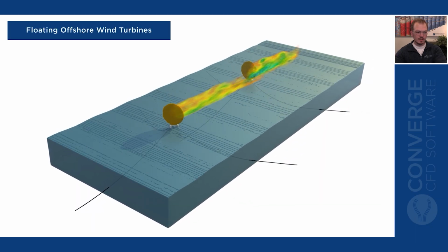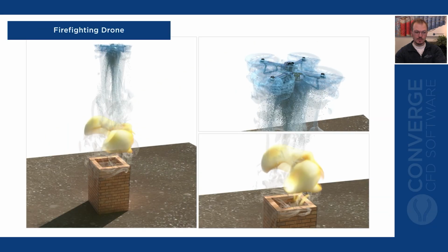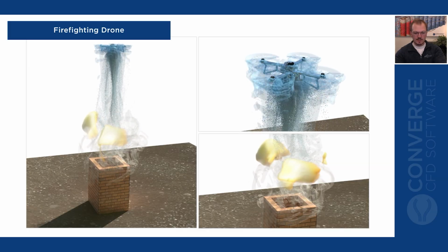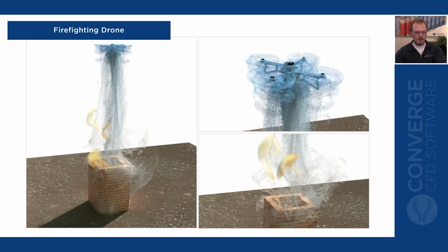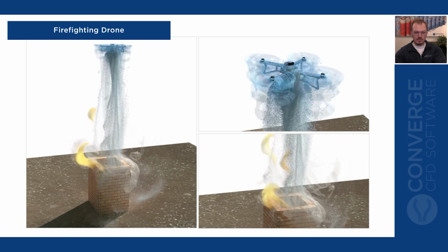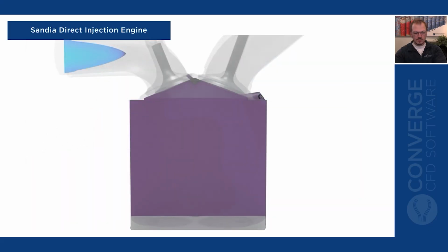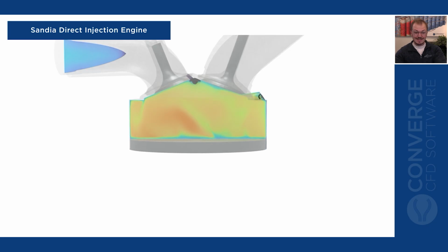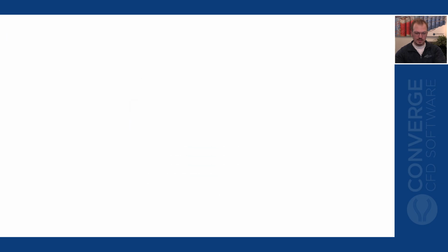These turbulent eddies occur at many length scales, even those too small for the discretized domain to resolve. To resolve the eddies occurring at the smallest length scales, you either need to refine the grid or use a turbulence model. The former solution is not practical for many applications due to its computational cost. This is where turbulence modeling comes in. Modeling turbulence allows you to account for the enhanced mixing effects of turbulence at a significantly reduced cost compared to directly resolving all the turbulent length scales.